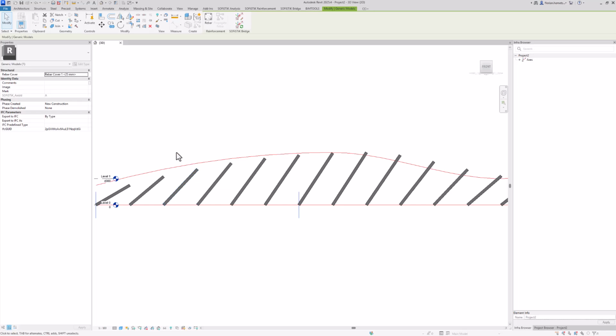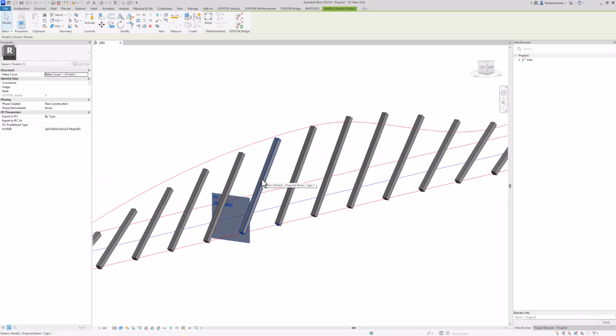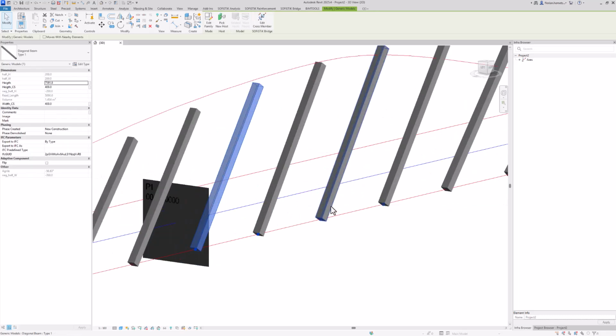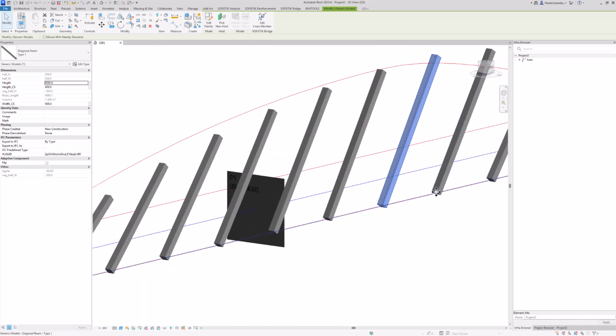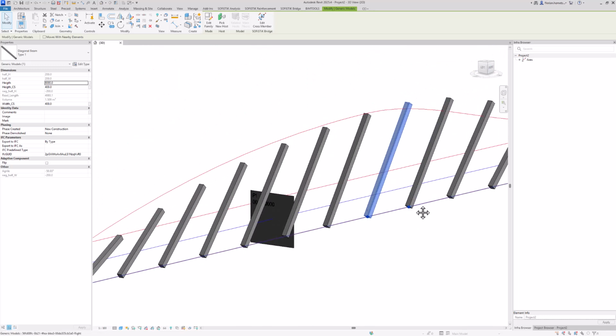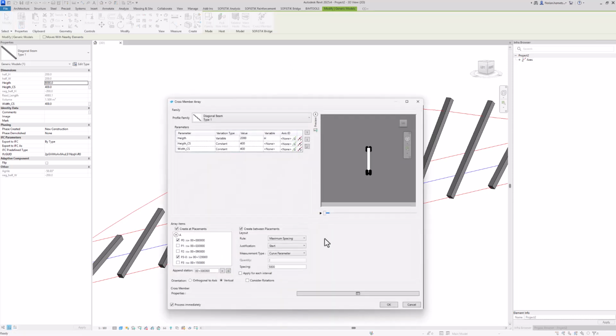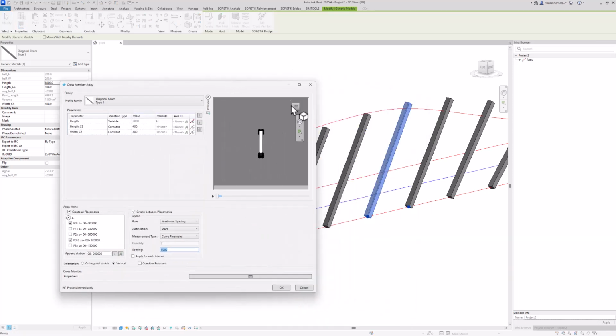Even though we perfectly defined everything, right? That is not completely true because we missed one crucial point. I always talked about a starting point. Here you can see number 1, and here is the end point with number 2, which is now placed in an interval of 5 meters. But the program does not automatically know that the point number 2 wants to read the height at the end